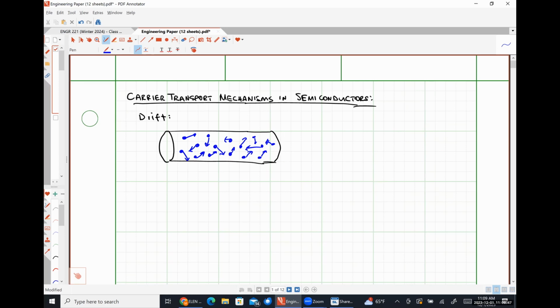So an electric field acts on charge carriers with this drift equation, where we're going to say our current density function, J drift, this is a vector, will be equal to Q times N times mu times E. Where, just to rehash some things I think we covered the other day, Q is the charge of an electron, negative 1.602 times 10 to the negative 19 coulombs.